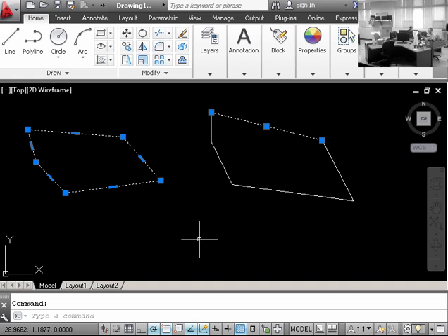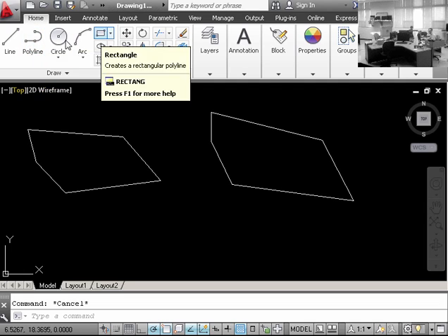That's what polyline is. Even though the command itself works just like line, it keeps all the segments combined. The reason that's important is because when CNC devices and any type of modeling look at lines, they don't like to see little segments. These are sort of broken to them. But software that deals with that kind of modeling likes to see polylines. So sometimes you draw in polylines, sometimes you draw in regular lines and trace it. Whatever the case may be, the polyline works to create stuff just the same way, and it's right next to the line command or wherever it's located on your screen.